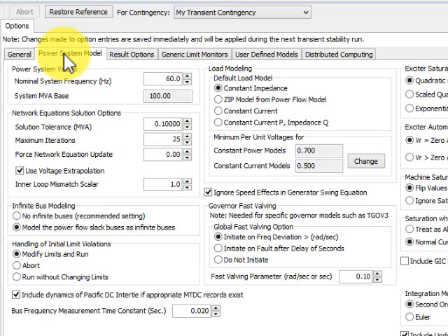The problem is we're trying to prevent people from having a problem where normally it won't occur, but if you put a fault on a bus that's got a constant power model in it, what do you want us to do when you're saying my load is 100 megawatts and my voltage is 0? What do you want? Yeah. So I think going forward, this would be a change for users like me to pay attention to this and put zeros when we're using a composite load model. Well, I don't know that you want that in the composite load model. Jamie will be talking about that on Thursday.